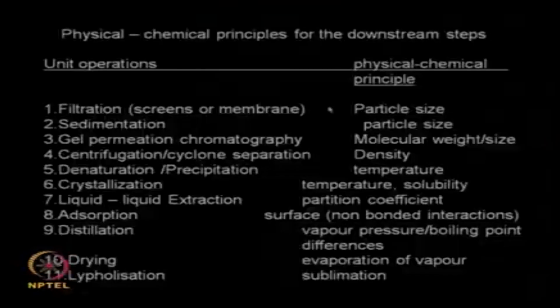This settling is called the settling velocity, and there is something called terminal settling velocity, and this terminal settling velocity depends upon the difference in densities between the liquid and the solid, and it depends on the viscosity of the liquid and on the particle size. Okay. So, again particle size comes into the picture. So, sedimentation is also based on particle size.